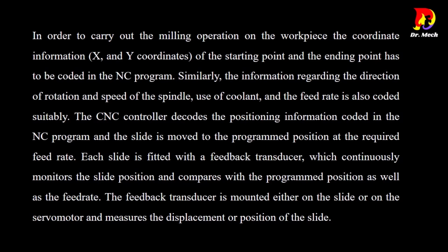Each slide is fitted with a feedback transducer, which continuously monitors the slide position and compares it with the programmed position, as well as the feed rate. The feedback transducer is mounted either on the slide or on the servo motor and measures the displacement or position of the slide.